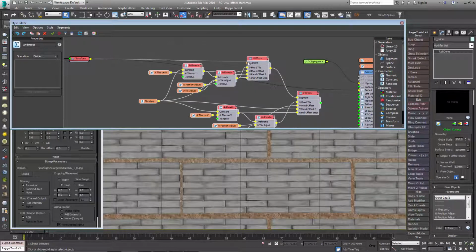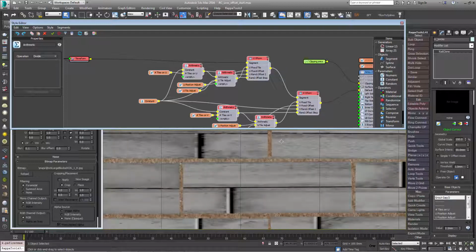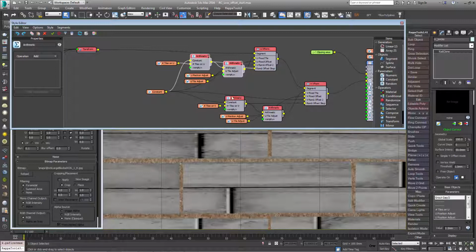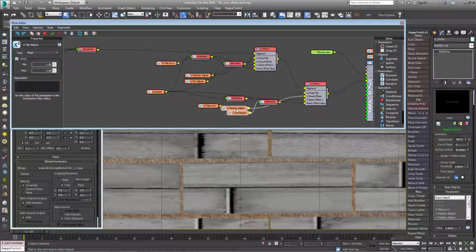Connect this group of nodes between the existing segments and the default input of the generator. And to make this graph a little simpler to read as we add more nodes, roll up the existing arithmetic nodes by selecting them and clicking Collapse from the top toolbar. This will hide the inputs and make the graph look less busy.